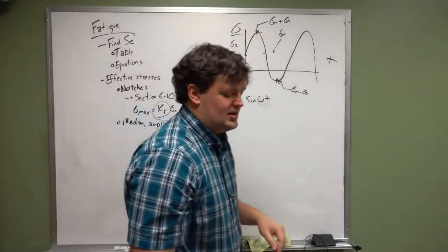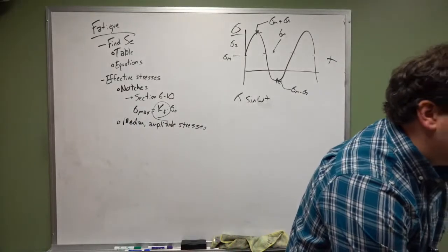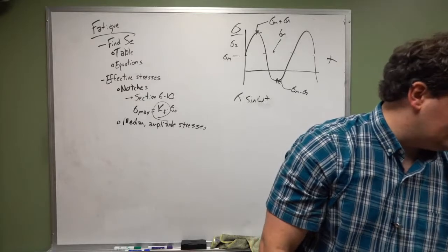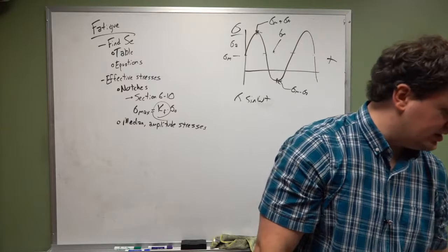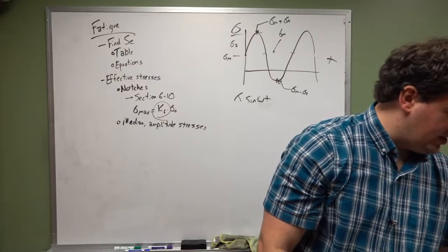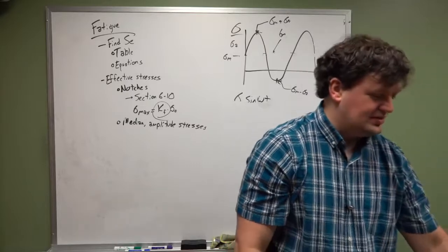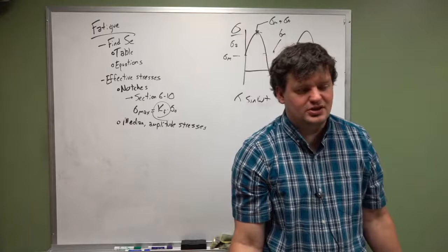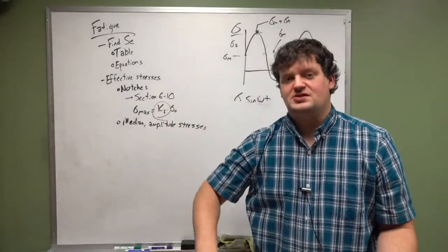This is only one little element that makes it slightly more complicated. The calculations for fatigue failure clearly state where sigma A and sigma M are, and it's just a matter of finding those stresses, which should be given to you somehow, that this is a maximum and this is a minimum.